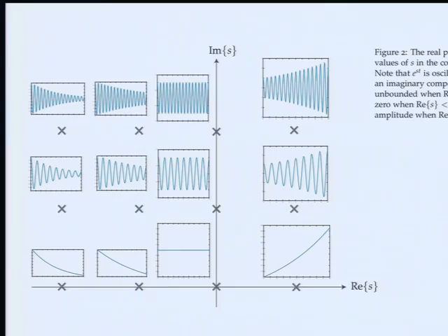So, poles matter. In fact, when we design controllers, you'll see some examples of this. Most of it is about putting the poles in the desired locations, right? How do you want your system to react to, say, a step change? Do you want it to oscillate, or do you want it to go smoothly to the new set point? That's all determined by where the poles are, okay?